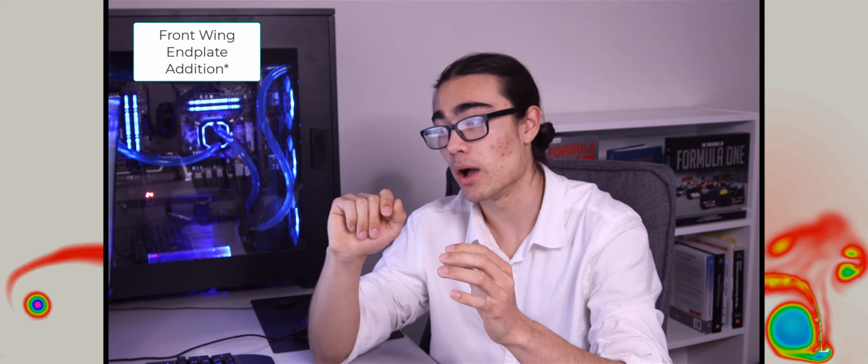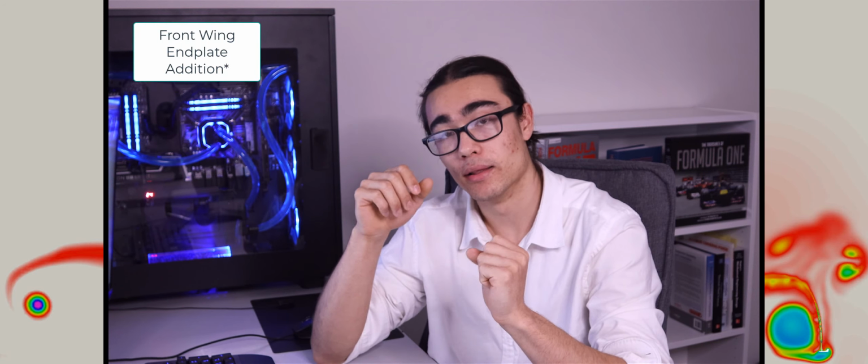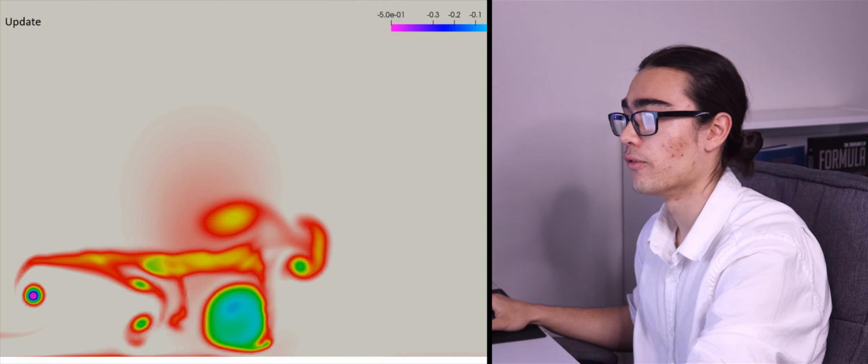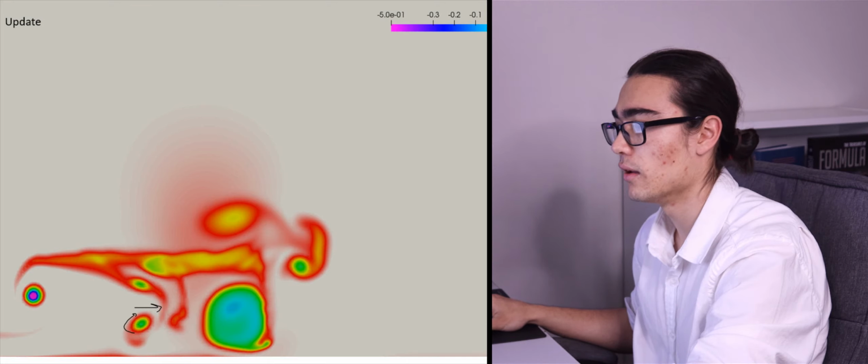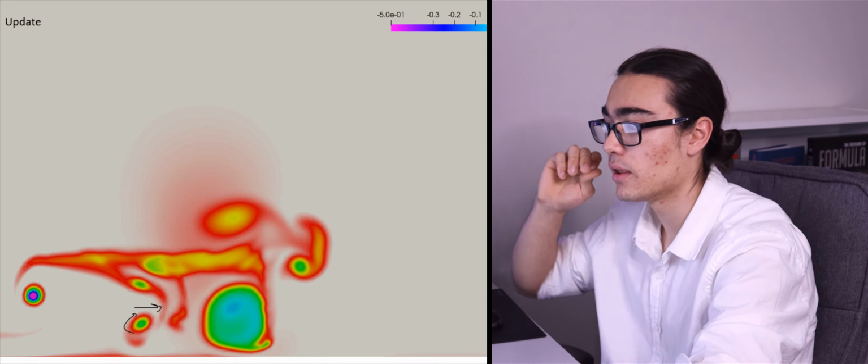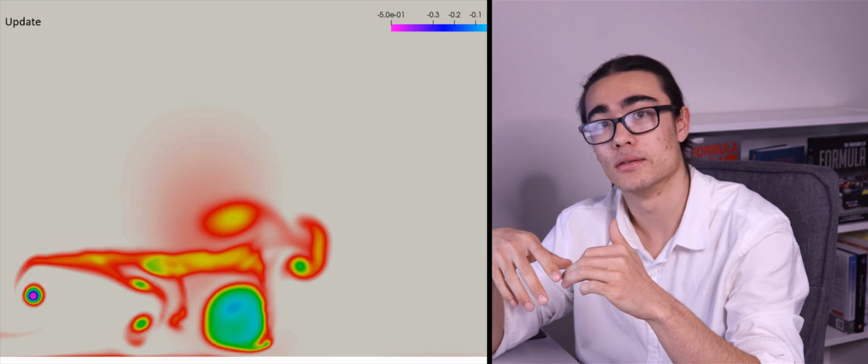Now, I'd say that a good chunk of this will be from the front wing end plate, but you will probably also see some lateral support from that strake, the support strake, the outboard strake that I put in. You might also see some support from this vortex, or these vortices, washing air off the strake and in, although this would be really quite slight itself. Also, with the strakes and the position that they are, sometimes you can get quite a good seal from them and generate a bit more localized load on your surfaces.